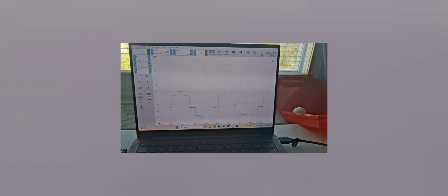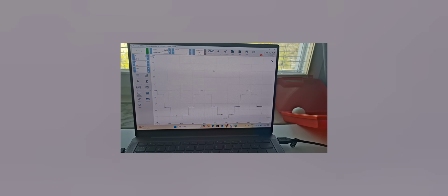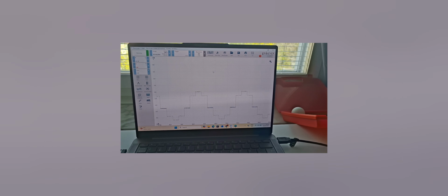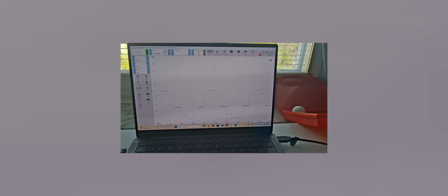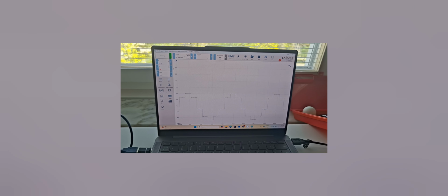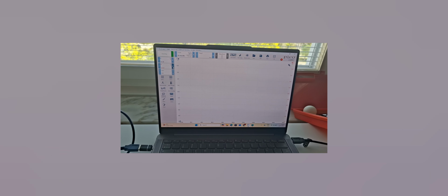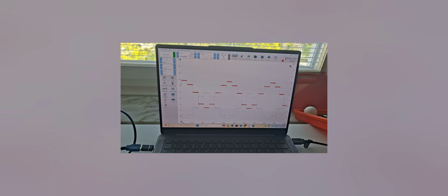As we can see on the picoscope, initially, before the voltage adder, we have a circuit that somewhat mimics a sine wave. It looks very blocky due to the fact that we only use 3 information bits, which isn't enough to properly approximate a wave, but we can see it does have a certain period. Now, after running it through the voltage adder, it becomes this red wave,